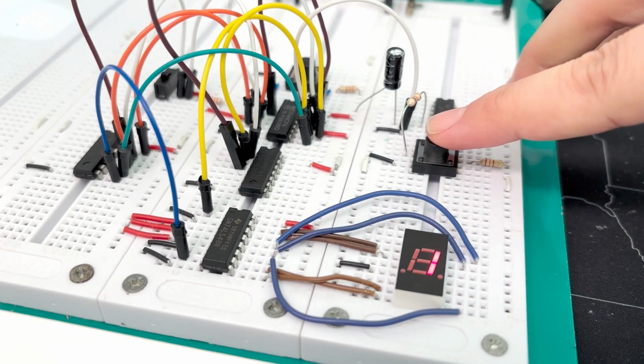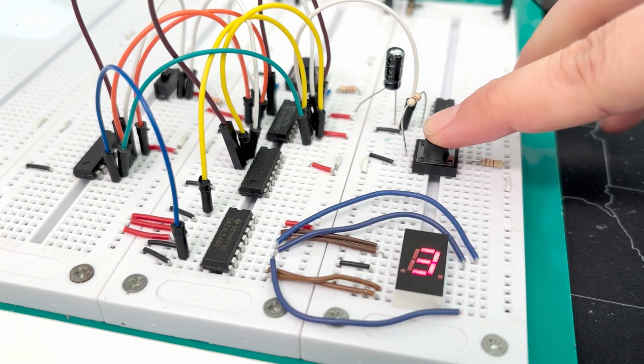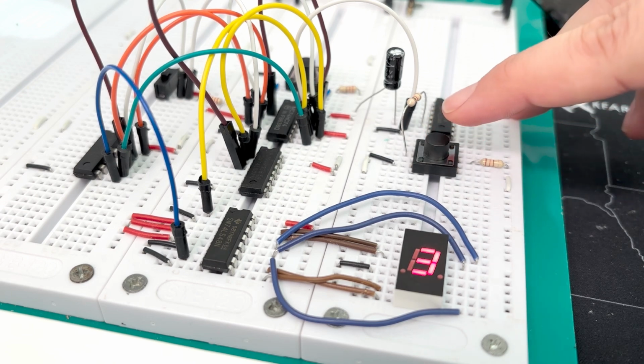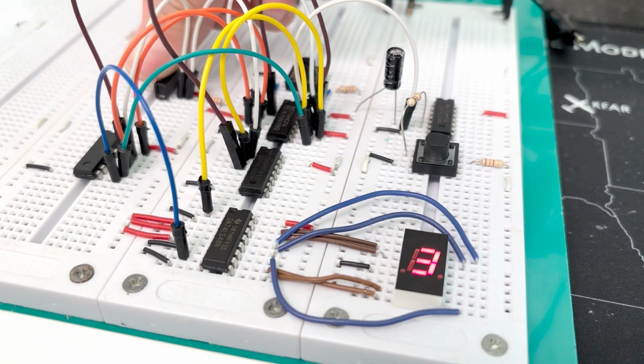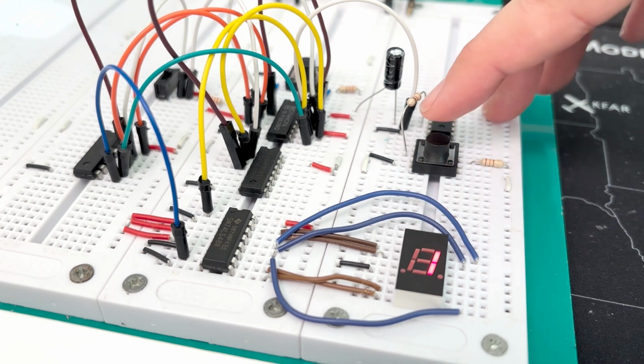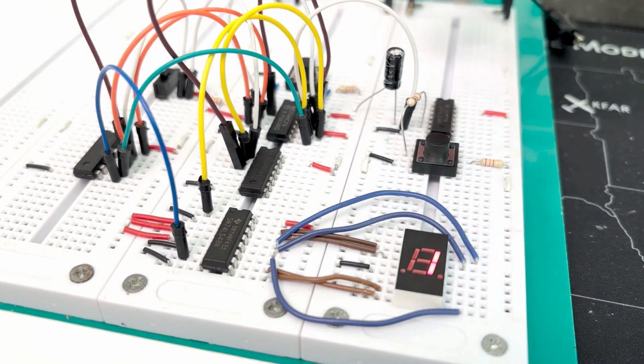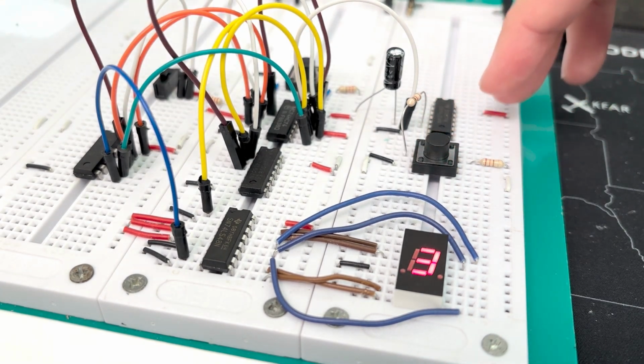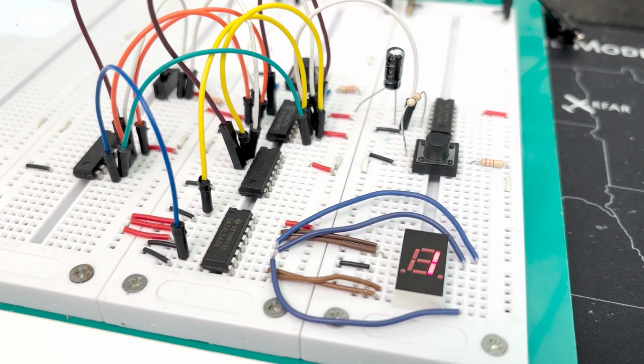I wired this up using the 7474 D flip-flop chip, a toggle switch for X, and a push button for the clock. A second push button can be used to asynchronously clear the flip-flops and put them into the reset state. I can confirm that the circuit follows the state diagram as expected. This specific example is a great use case for a Moore machine because the output has no need to ever change until the clock ticks and the circuit enters into a different state.